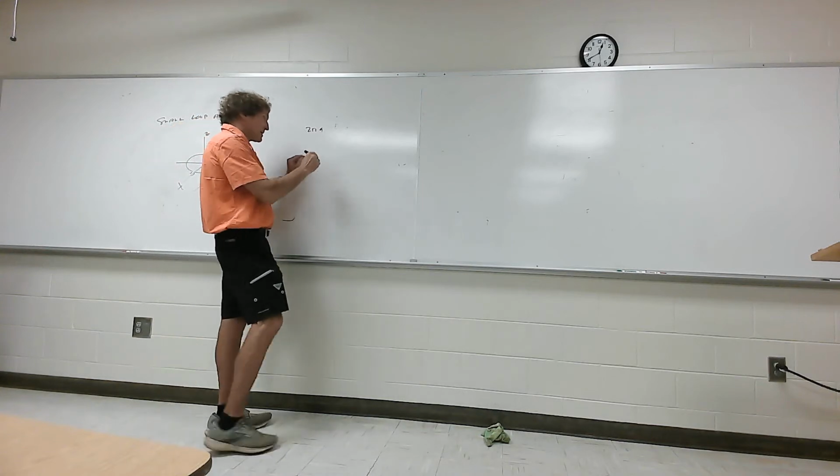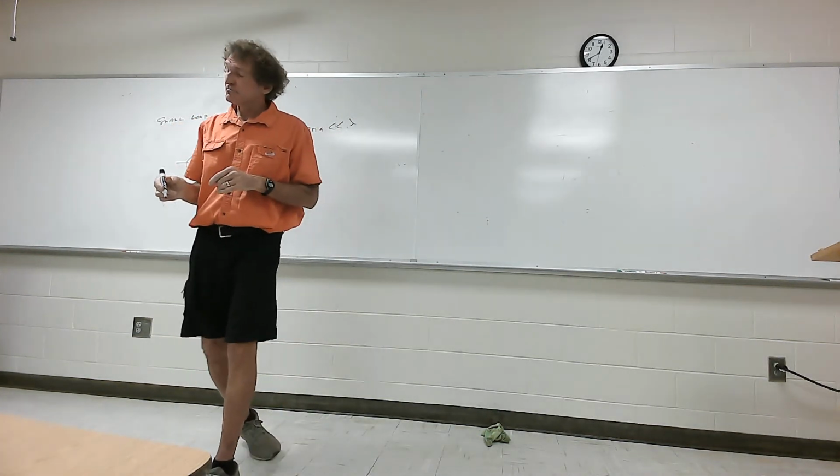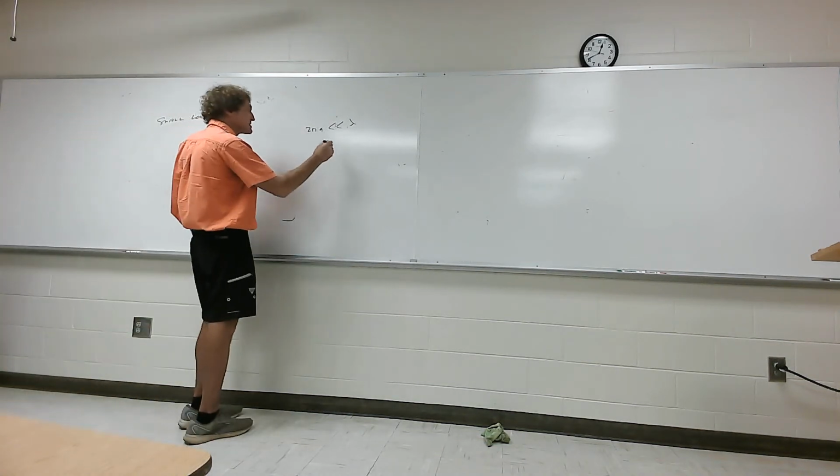That has got to be much less than a wavelength. Technically, it's less than 1/10 of a wavelength. It's like if you cut that antenna and straightened it out, that would be like a short dipole antenna, and that means the total length would have to be less than 1/10 of a wavelength. He has a different criteria. I think he has this in his book.